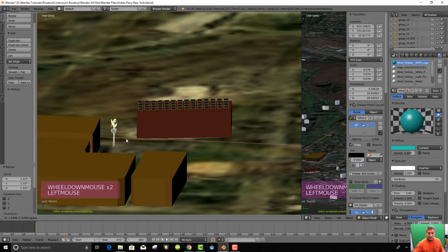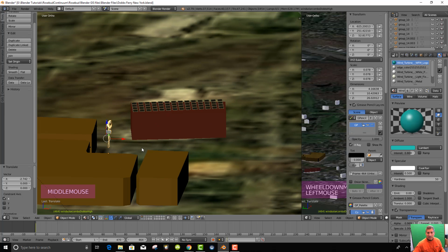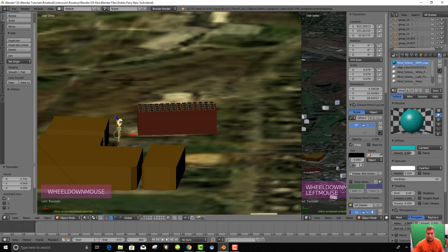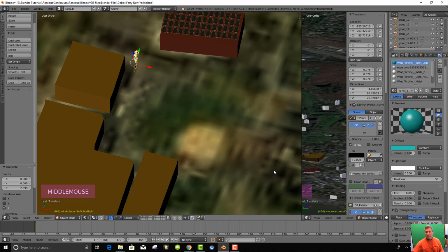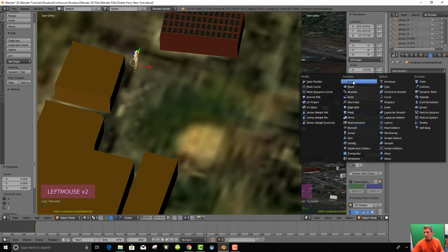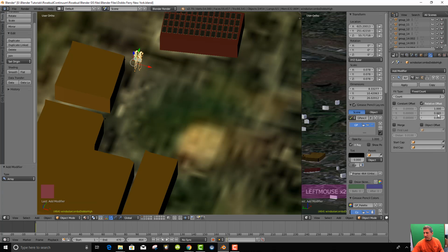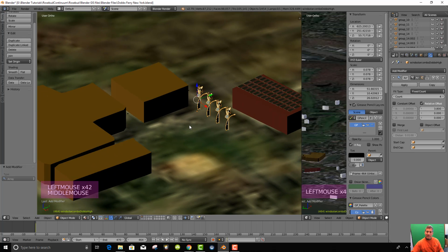And again, we can use the array to make sure that they're nice and neat, and I don't have to spend the time duplicating. So we have it selected there. It's sitting in the landscape, and I can now take it and go to a modifier and go to array, and there it is, and I can make my offset just a bit bigger, and then I can do more than 2. I think they have 4, and I think they're spread out wider. So instead of using 5, let me go 4 and spread them out through the parking lot. And there you are.